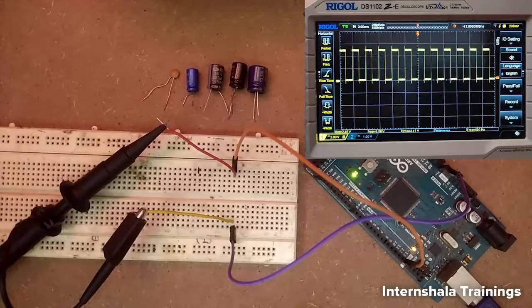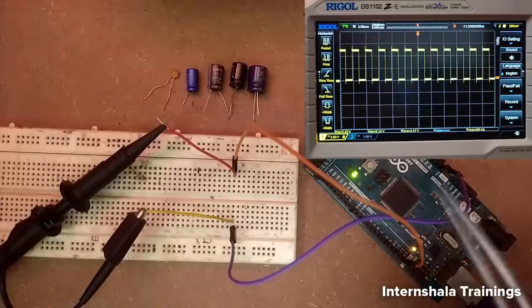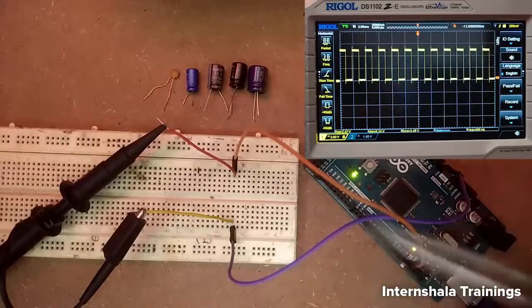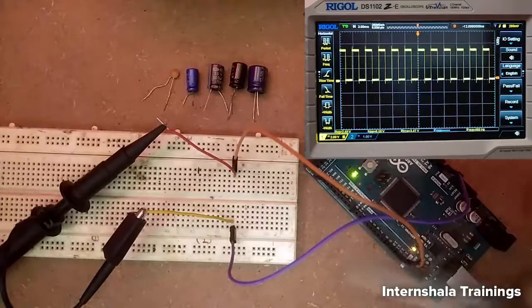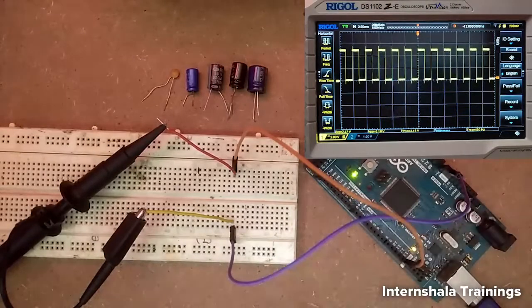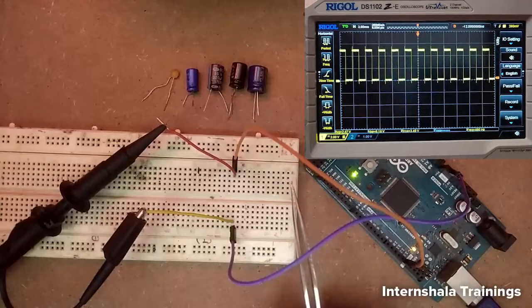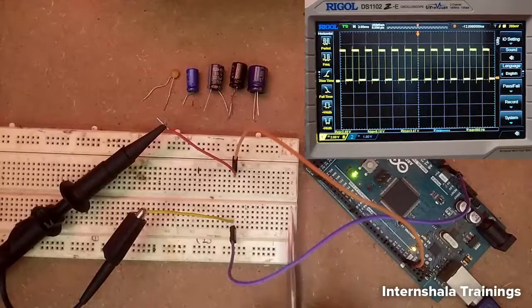Another important point that I want to tell you here is, you might have observed audio amplifiers. In an audio amplifier, the frequency is around 20 Hz to 20 kilohertz. That's the reason we need to use a bigger capacitor to filter out those frequencies, and that's actually why audio amplifiers are bigger. However, RF amplifiers are very compact.